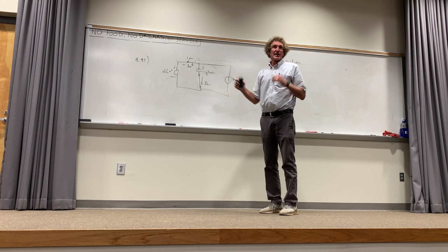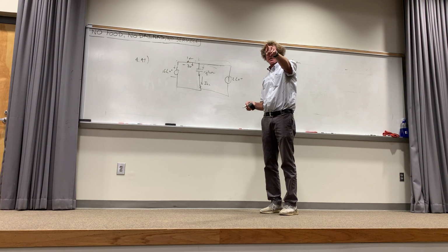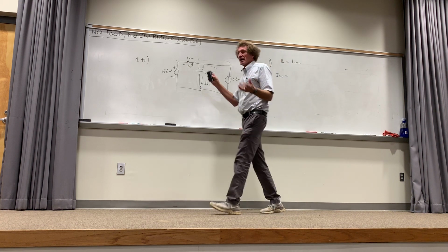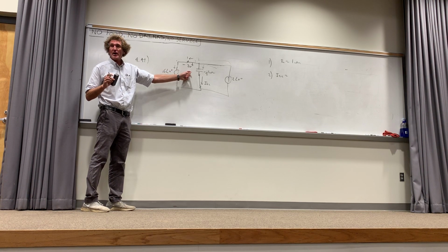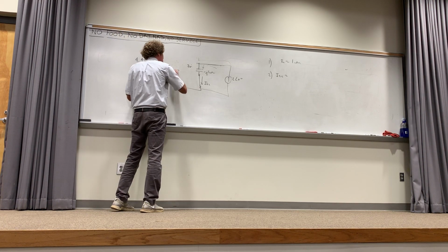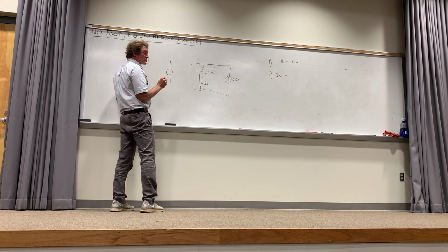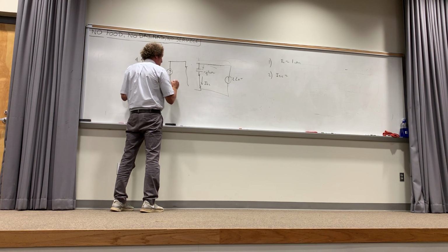I'm going to just show you guys a quick one. I mean, I've done these too many times. Now, somebody, I think the guy that said use a source transform or something like that. But here's the thing. Do a source transform right here. You see how you got 6 and 2 ohm and 1 ohm, right? Just make that, watch this. This becomes simply, now it's 6 volts by 1 ohm, or 6 amps, right? At 0 degrees. Now I put the 1 ohm here, correct, class?